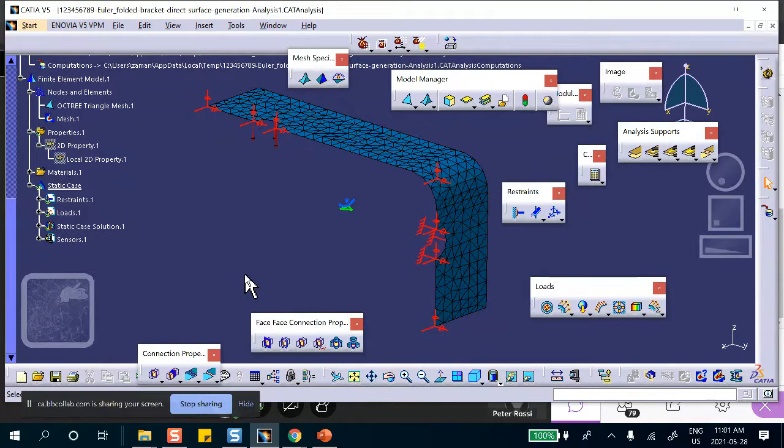Now, by the way, if your job was to design that fillet, that corner, if your primary responsibility was that area, then you're not going to use shell elements. You're going to concentrate on that area and use solid elements just for that area. Yeah, okay, that's what I figured, but I wasn't sure if CATIA accounts for it or not. No, it doesn't. Any other question before we move on and do it the way the book does it?